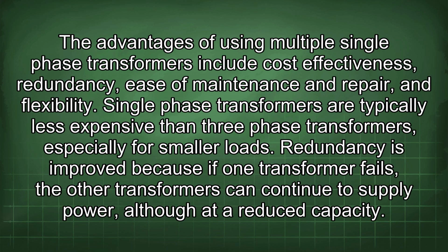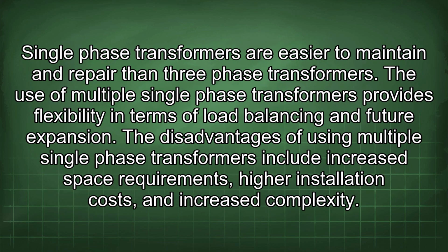The advantages of using multiple single-phase transformers include cost-effectiveness, redundancy, ease of maintenance and repair, and flexibility. Single-phase transformers are typically less expensive than three-phase transformers, especially for smaller loads. Redundancy is improved because if one transformer fails, the other transformers can continue to supply power, although at a reduced capacity. Single-phase transformers are easier to maintain and repair than three-phase transformers. The use of multiple single-phase transformers provides flexibility in terms of load balancing and future expansion.